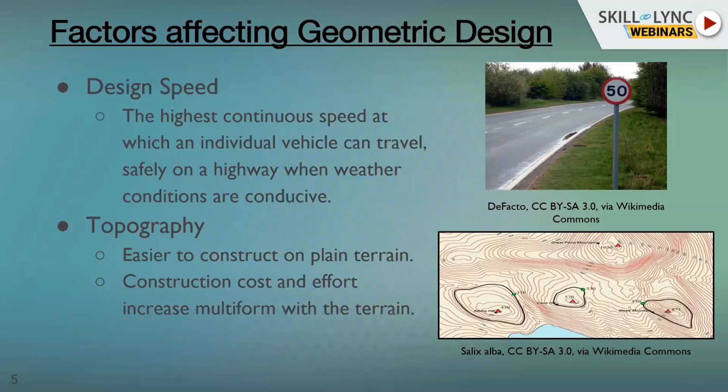You might wonder, right? So when you're traveling on a highway, I mean on a free road, then the curve radius is more. Okay, imagine you are approaching the intersection and you want to make a U-turn. While making a U-turn, you obviously reduce your speed. So when you reduce your speed, then you can turn your vehicle in a small radius, right? So this is what happens. If you are traveling at 100 kilometers per hour, the radius is going to be large. So that is how it impacts the design there.